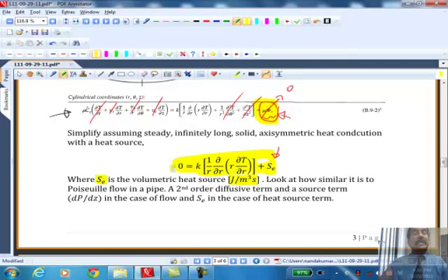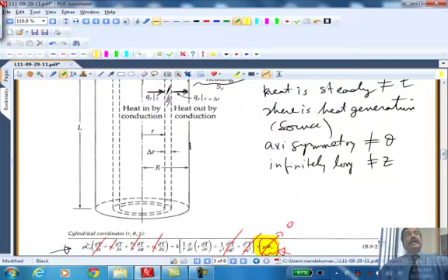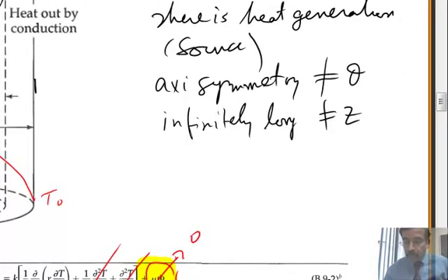So what we are saying is, if I plot T, this is for example some temperature T0 on the surface. I'm maintaining the outside surface exposed to room temperature T0. Inside, the maximum is going to occur at the center. Does that make sense? That's because that plane, that axis, would be an axis of zero flux. The temperature is maximum there.